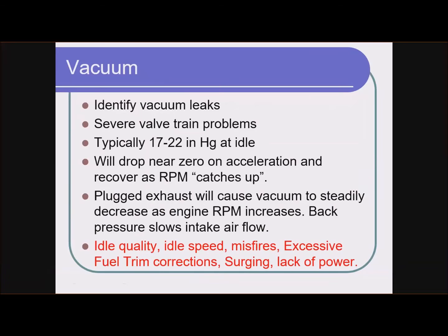One way to verify a plugged exhaust is to physically disconnect it. So if you think your catalytic converter is plugged, disconnecting the exhaust in front of that catalytic converter should make the problem go away. Obviously, it'll be loud, but you'll have good vacuum and good acceleration again. It may be enough to simply remove an oxygen sensor, and that'll allow enough exhaust to escape out that oxygen sensor hole that it makes a big difference. So those are two things you can do to try to verify a plugged exhaust.